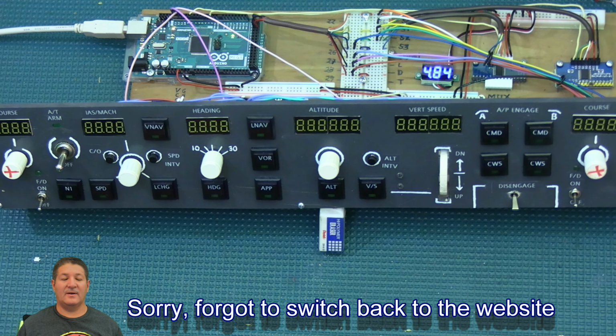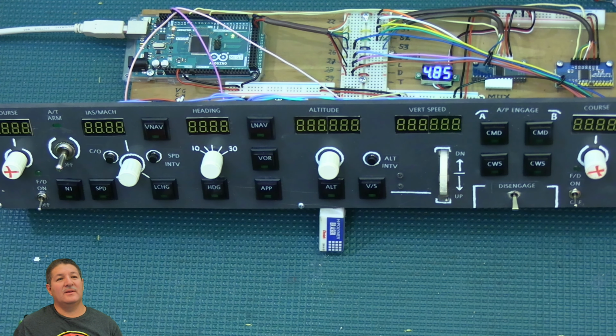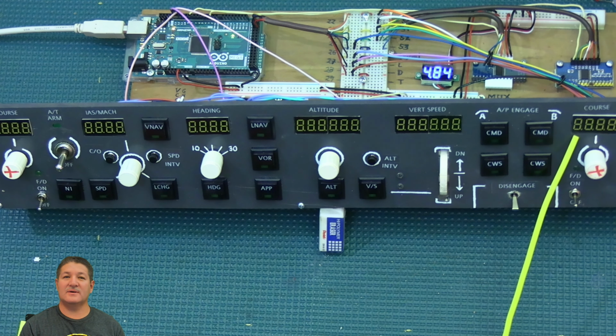You might get it all out of sequence, or you might not get anything at all. So you've got to make sure that you select the right type of display here. All right, so now we can go ahead and assign the vertical speed on that one, and we're done with that one. Now we're going to do the one on number 10, assign a 7-segment display, and going back to our panel, we can see that that's a 4-digit TM1637 on that one.